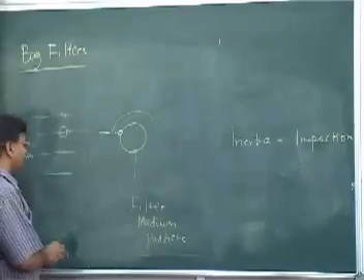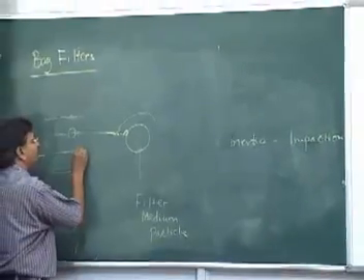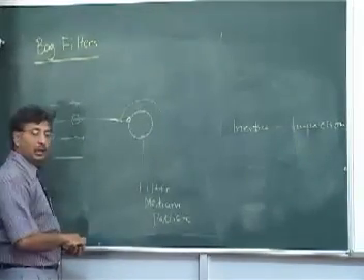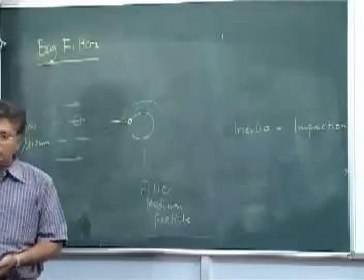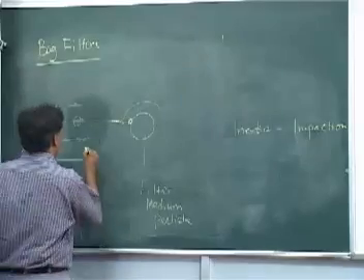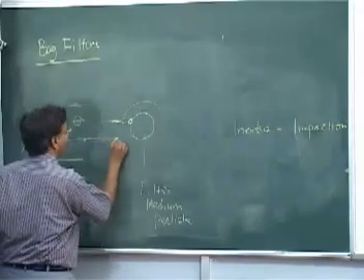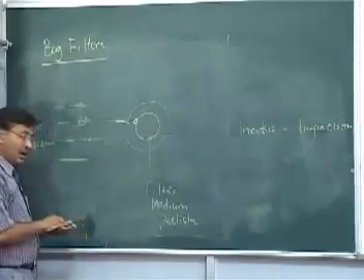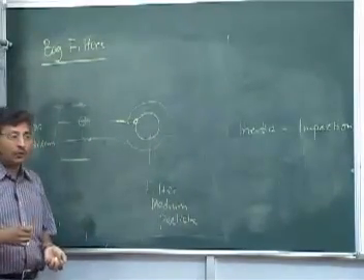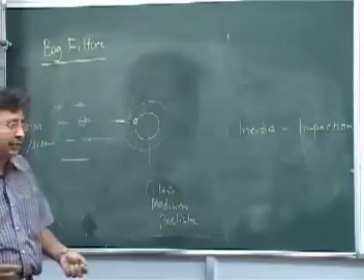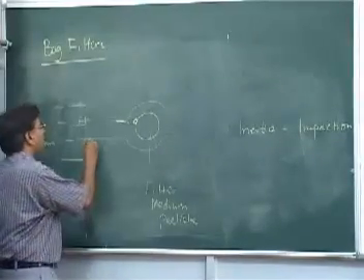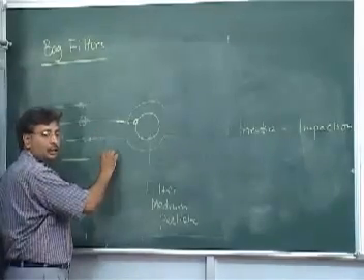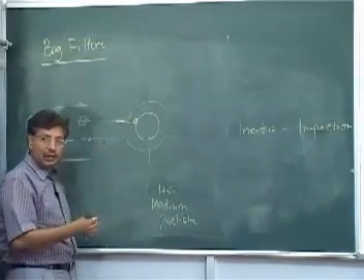Second thing is, let's say a particle is very small. Okay, it will hardly have any inertia. So the gas stream will go like this. This particle being very small, sub-micron size, 0.1 or something like this, will have some kind of motion, what is that? Brownian motion. Very small particles will have Brownian motion.